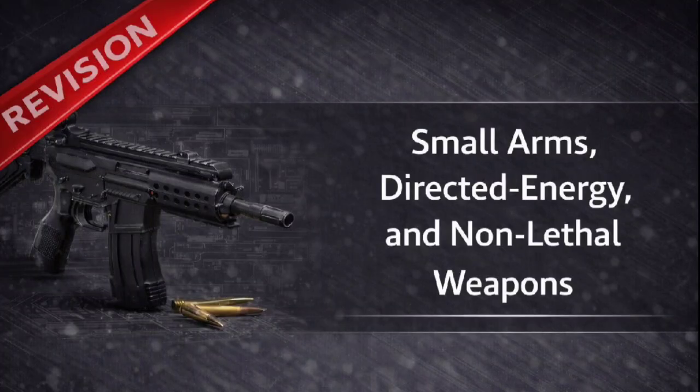And the mechanism driven by that gas comes in 3 distinct types. Let's compare them. We can begin with the long-stroke piston. Here, the piston is physically connected to and moves the full distance with the breech block. Okay, a single moving part. Yes, which makes the system extremely robust. It's very common in machine guns. But the heavy, long-moving parts significantly disrupt the stability of the weapon. Which is why it's not ideal for a rifle, leading to the preferred system, the short-stroke piston.